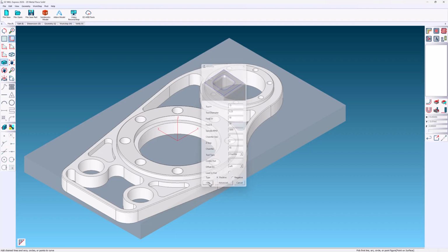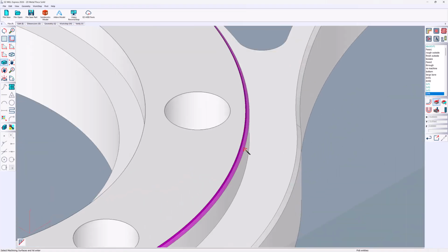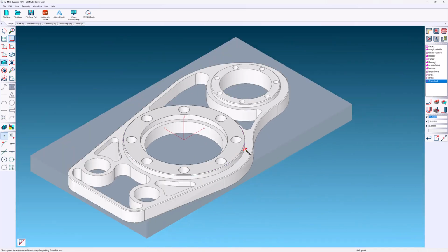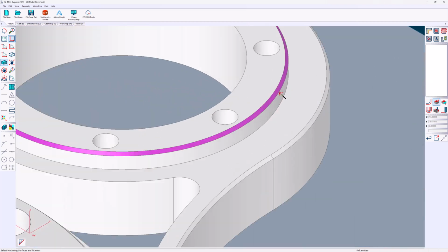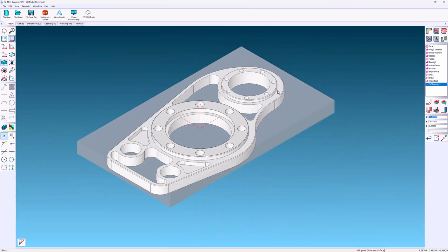SmartClick is activated for chamfers using the button just above our simulation icon. Because all the information for our other chamfers is the same, I'll duplicate the operation and swap out the faces. To remove the prior face selection, simply click outside the part and all the faces are removed for you to select new ones. Duplicate as many times as needed.